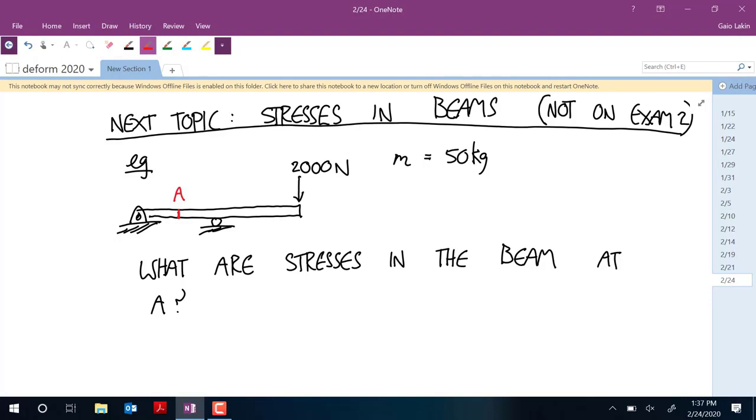And so even specifying that we want to calculate the stresses at this level along the beam left and right, we have to represent the stresses along the cross section as some kinds of functions of the y and z components. But that's what we're trying to get to, basically.